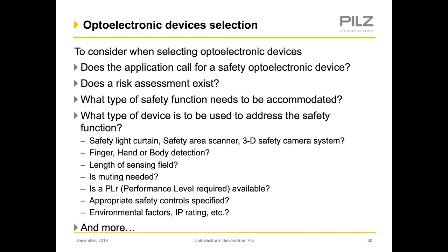What type of safety function needs to be accommodated? What type of safety device is used to address the safety function? So here is, of course, all the different types that we have, all the resolution, length of sensing field, is muting needed, what performance level required is available, are appropriate safety controls specified, did we consider environmental factors, IP rating and the like, and possibly more.